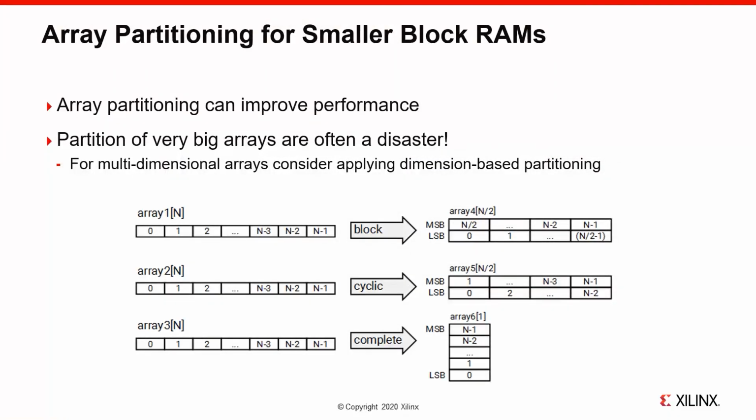By default, the Vitis compiler maps large arrays to on-chip memories on the programmable logic. Memories store data efficiently, but with limited access ports, they can limit the performance of the application, the memory bandwidth. All the elements of an array can't be accessed in parallel when implemented in a memory. Depending on the performance requirements, you may need to access more elements of an array than a single on-chip memory block allows.